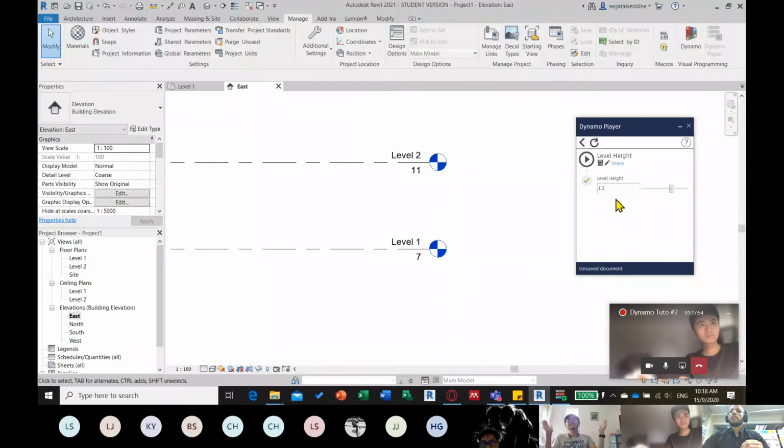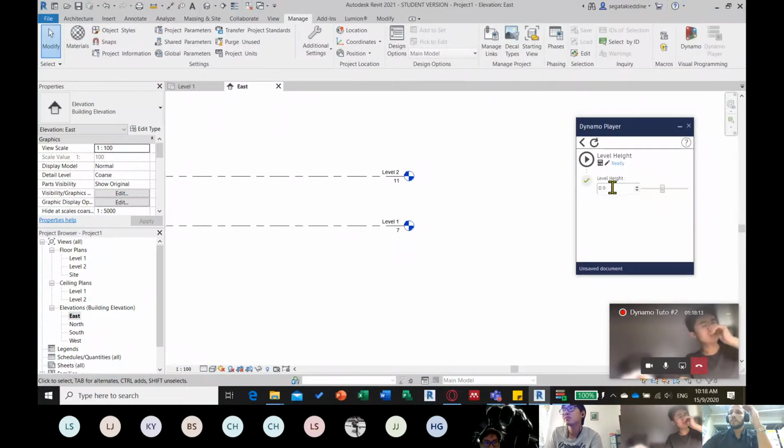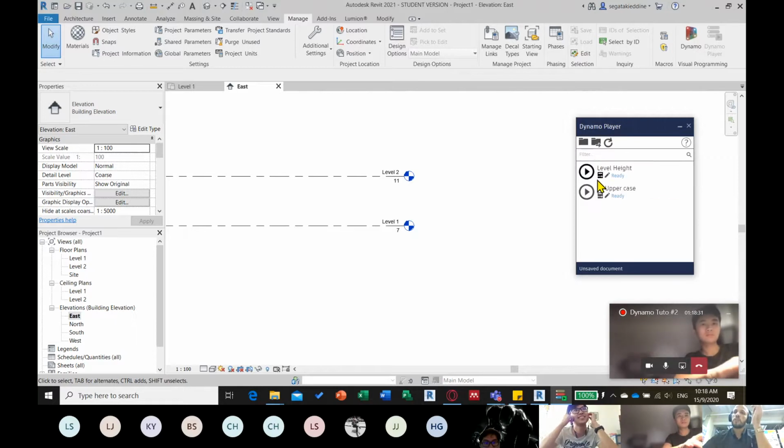This means even when you create massing with all these constraints, you can call them A, B, C, and D, etc. And since you can modify them, they are parametric, you can create sliders. After that, you will see only your massing here with a very cute Dynamo Player with all these sliders. You play whatever you want, and you know the names. This is A, this is B, and this is C. So it's really helpful in many ways. So the trick, again, is when you edit the script,